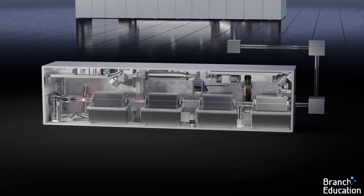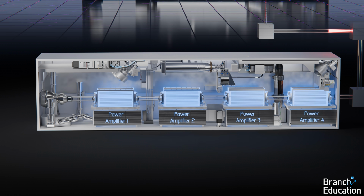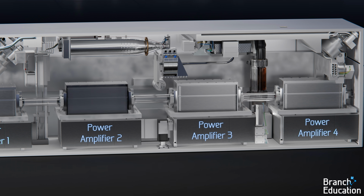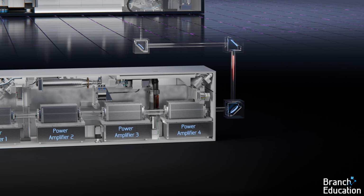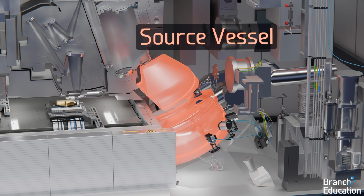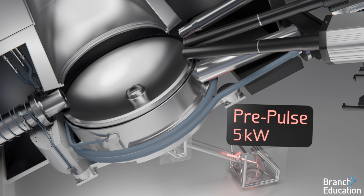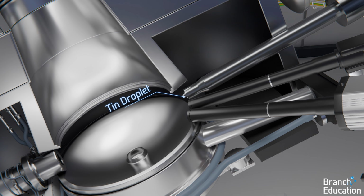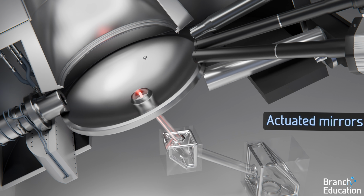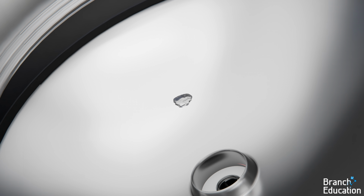To start, two high-powered laser pulses run through multiple amplifiers below the cleanroom floor. These laser pulses grow in power and then travel from the subfab using a pathway of mirrors and up through the bottom of the tool and into a chamber called a source vessel. The first laser, called a pre-pulse, is around 5 kilowatts in power and is targeted at a droplet of tin using a set of actuated mirrors. This pre-pulse laser turns the tin droplets into a pancake-like shape.